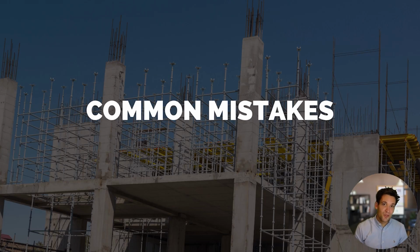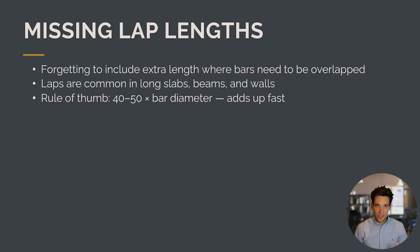Okay, so let's finish off with some common mistakes people make in steel reinforcement takeoffs. In addition to the two I've already done in this video, which is using the wrong ratio when using the ratio method and not factoring in starter bars when I did the manual method. The first one, which I've mentioned a couple of times, is missing the lap lengths. Remember, if your prefabricated bars are shorter than the length of the slabs, you have to factor in overlaps between the bars.